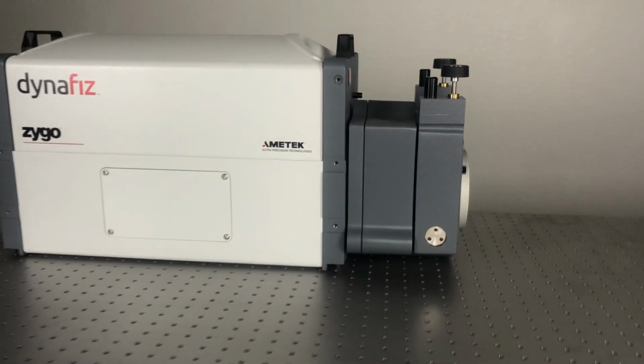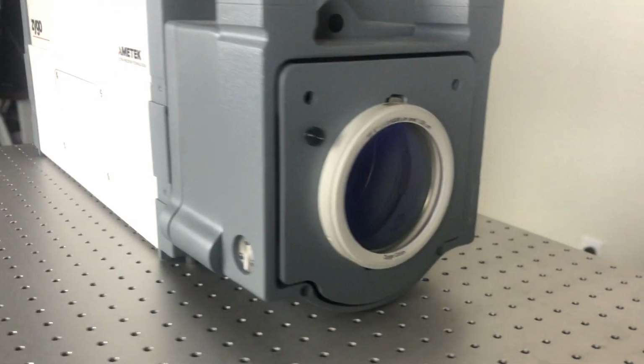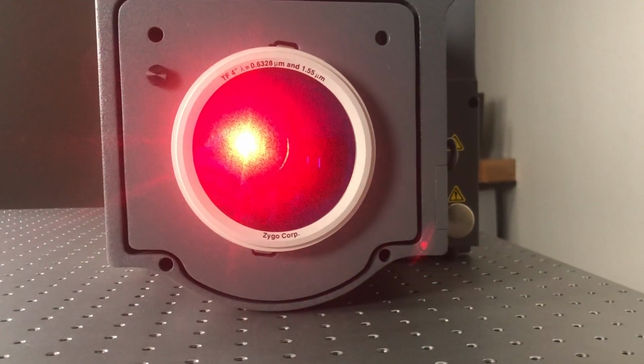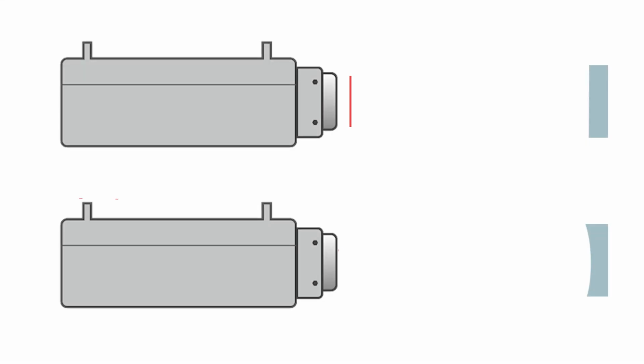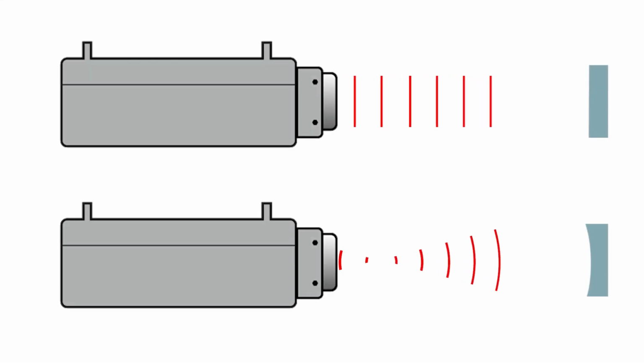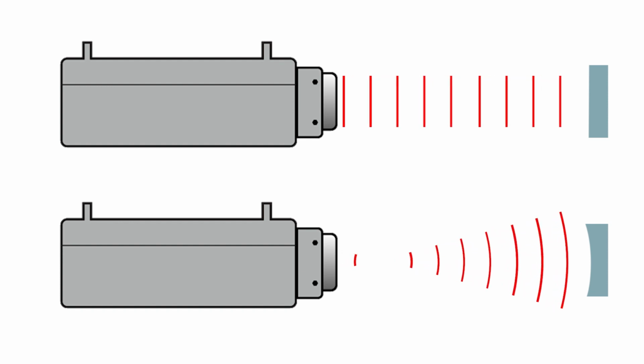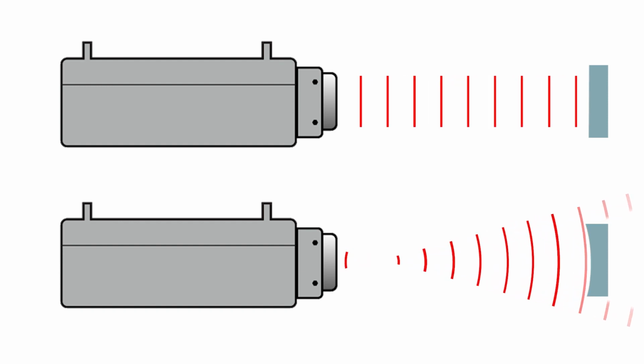Interferometer has really nice parameters. It's fast, it's high resolution, full aperture, and very high precision. However, it's limited in the dynamic range of the shapes that it can measure. It's generally limited to spherical and plano surfaces.